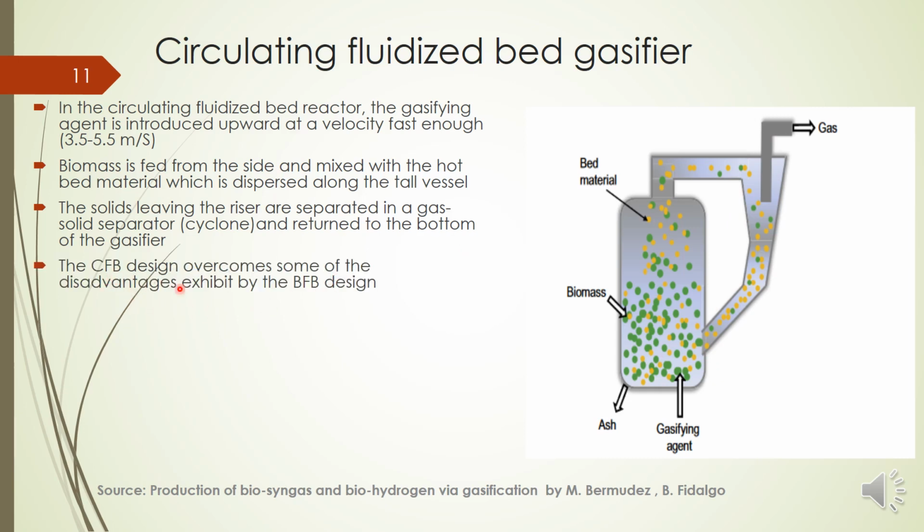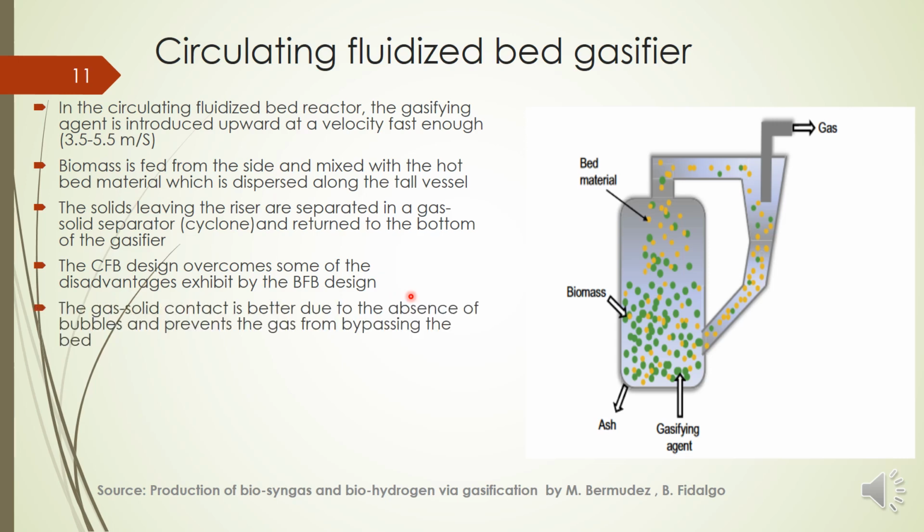The main advantage is that this CFB design overcomes the disadvantage exhibited by bubbling fluidized bed. Due to the better gas-solid contact and absence of bubbles, this prevents the gas from bypassing the bed.